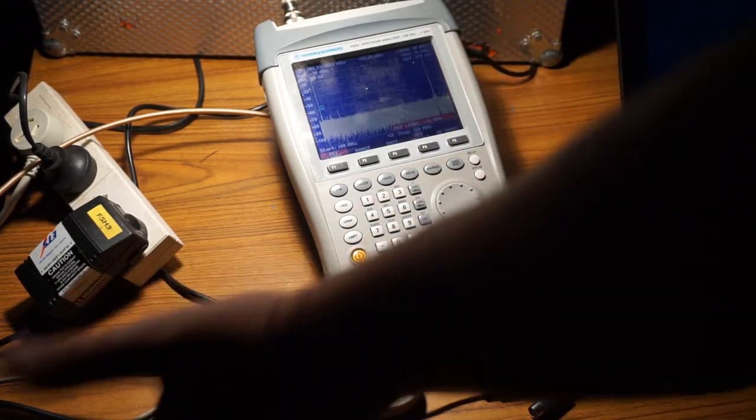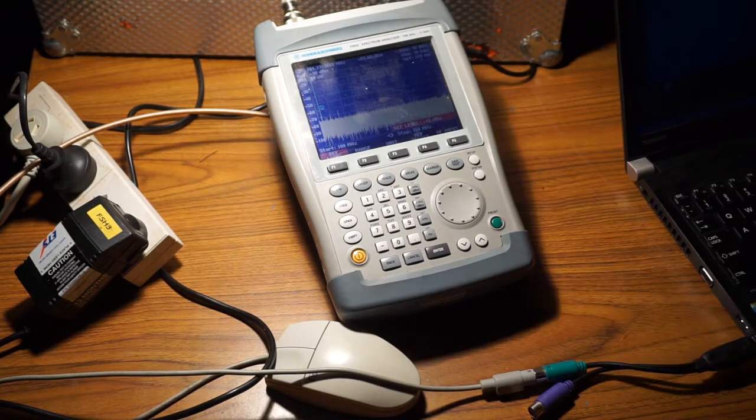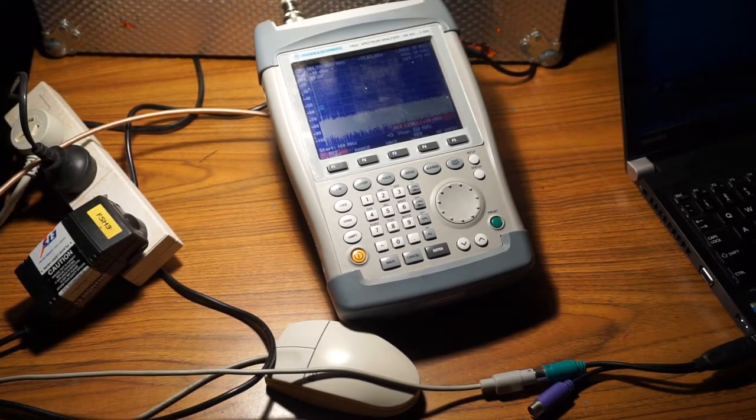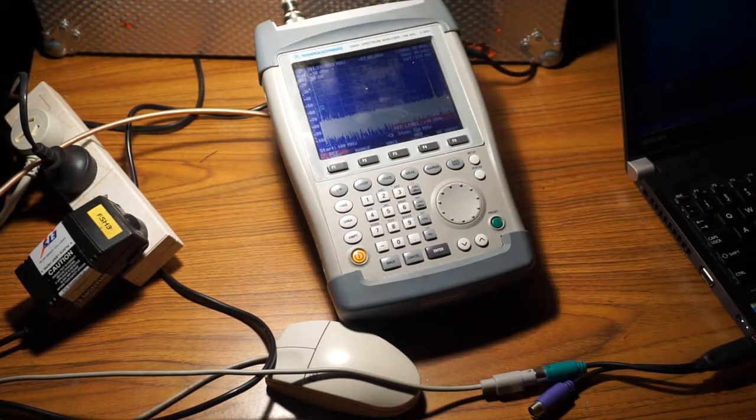Connected into an instrument, or typically into a transmitter. People leave it connected into a transmitter and then actually transmit into it. I don't know why they do it, but I've seen it happen a number of times. People say, "Oh, I won't transmit, I'll remember not to transmit," but they do. So you can directly connect a transmitter, but you need suitable power attenuators to attenuate the power down into it, so you don't destroy it.